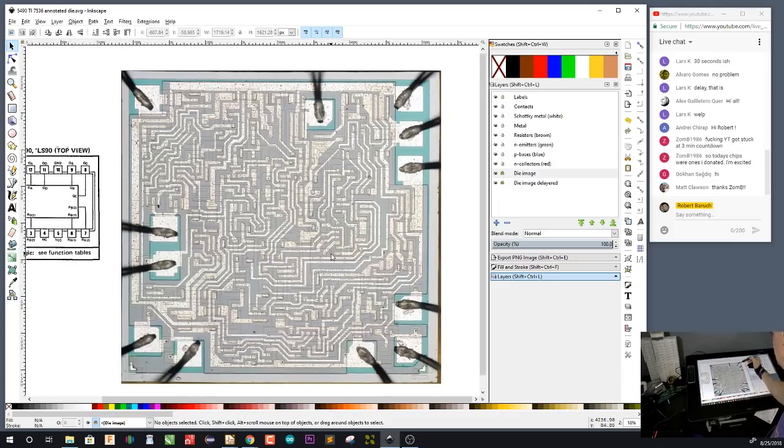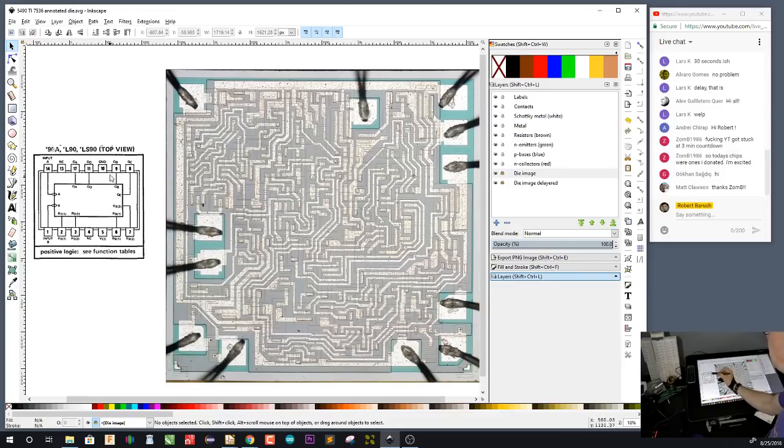So immediately we can probably say that this pad at the top right is ground. To verify that, you can look at the pinout and start counting and see if it looks correct. Because if you count and look at your VCC pad and it also looks like there's a bunch of metal feeding into a lot of things, then you've probably got the right pin ordering. So if we look at this pad, that's pin 10, right? And then, let's go around this way. We have pin 9, that's this pad. Pin 8 is this pad.